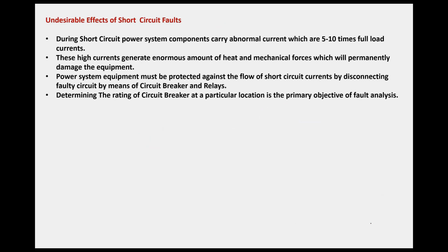Okay. Last discussion for today is, what are the undesirable effects of the short circuit faults? During short circuit faults, the power system components carry abnormally high currents, which are 5 to 10 times full load currents. During a short circuit, the current has to be generated from the generator and it has to flow through all the components that are connected in series to the point.